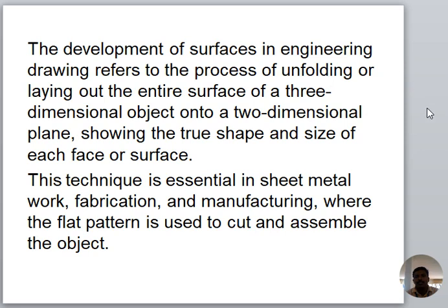The development of surface in engineering drawing refers to the process of unfolding or laying out the entire surface of the three-dimensional object into a two-dimensional plane, showing the true shape and size of each face or surface. This technique is essential in sheet metal work, fabrication and manufacturing, where the flat pattern is used to cut and assemble the three-dimensional objects.